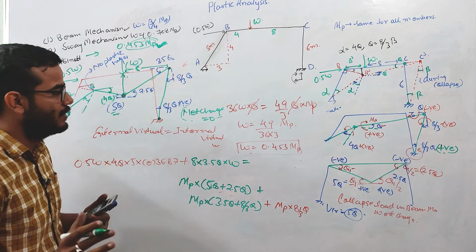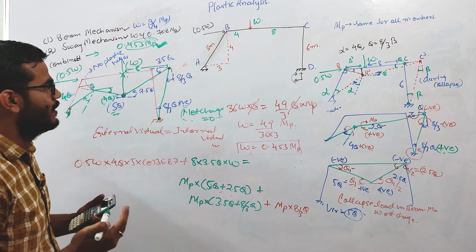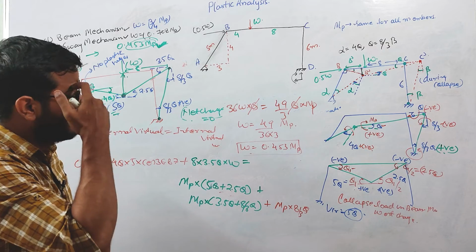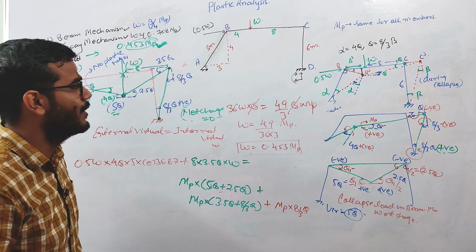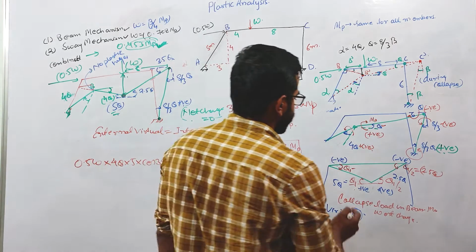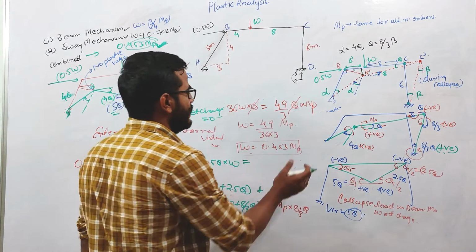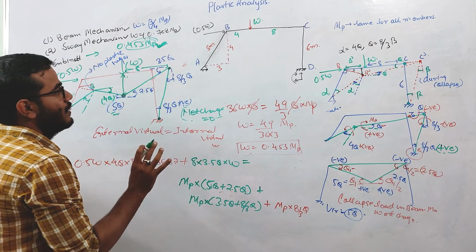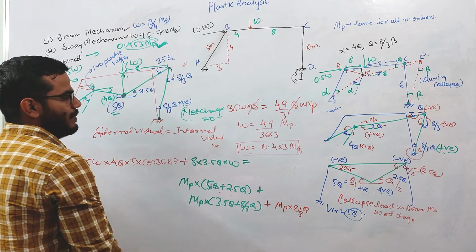So this is the problem. It is a little different problem here because there is an inclination of the column. I hope this problem is clear to you. There are some very good concepts over here, such as how to check the sign of the rotation, because it is easy to understand. In combined mechanism, we simply combine those rotations, and we see how the members are rotating, basically.